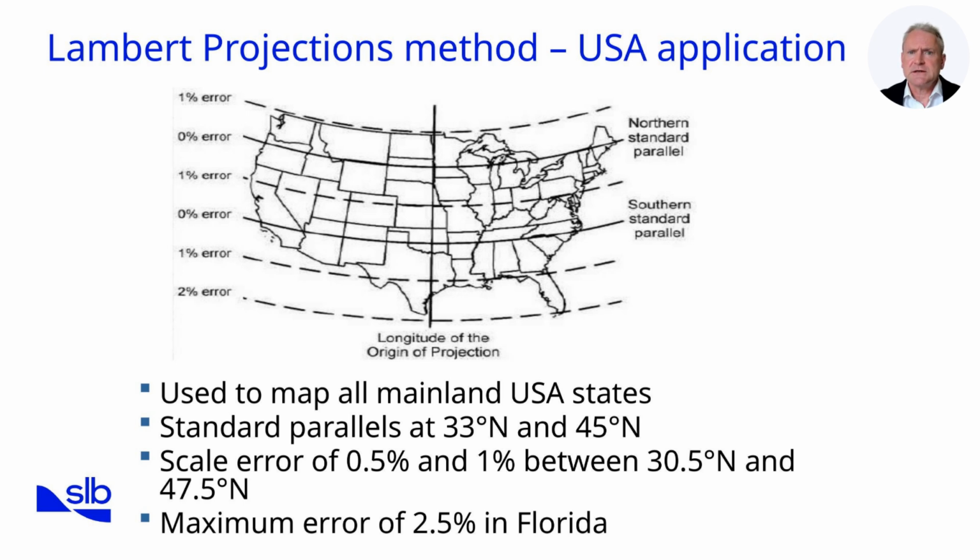This reinforces the importance of understanding the assumptions behind the map projection you are working with. Even within a single country, different states may use slightly different configurations. In oil and gas, precision matters. Being off by a few hundred meters could mean missing a target reservoir or drilling into the wrong lease block.